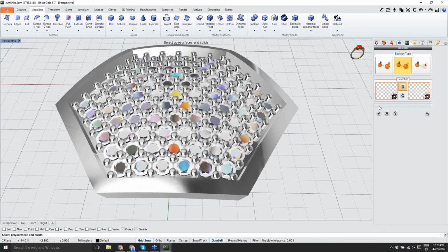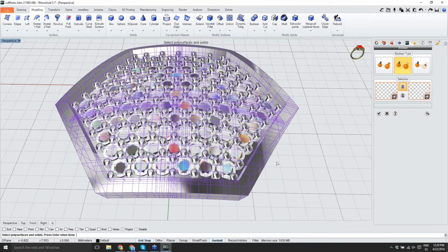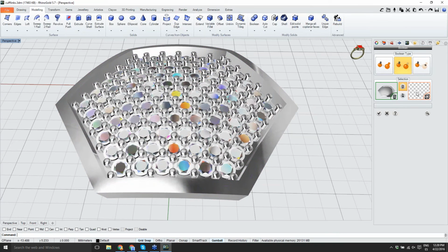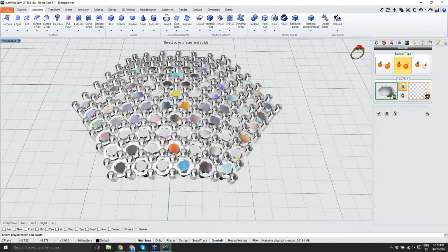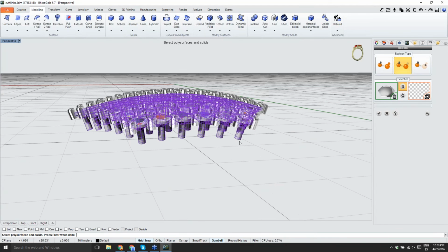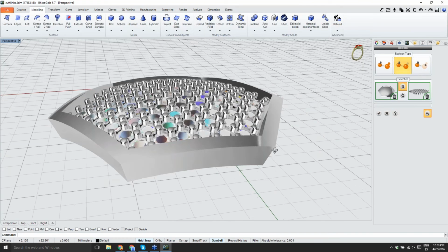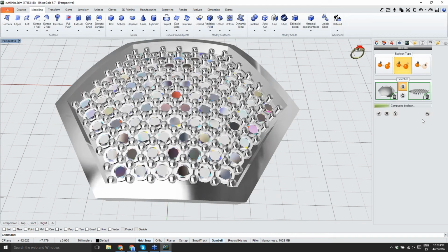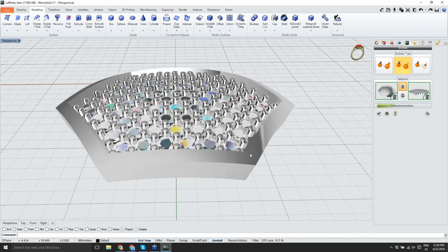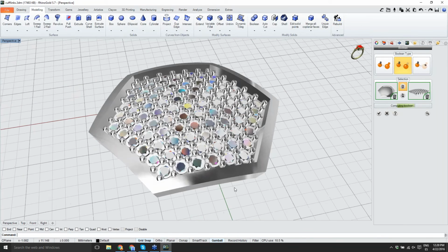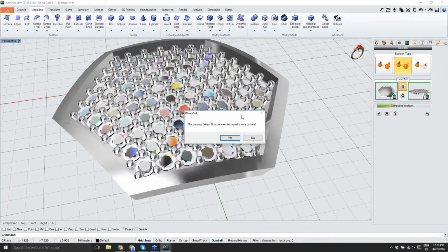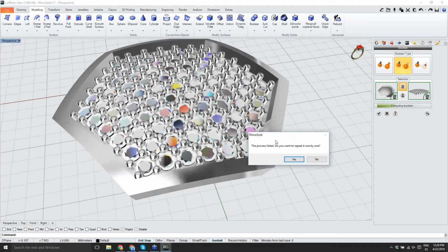And of course now I need to select my object. So first selection box, the base object, the object I want to keep, enter. And then the second selection box, I will define my cutter. So I select my cutters, enter again, just follow the instructions in the command line. And now I just click on the preview icon to calculate my Boolean operation.